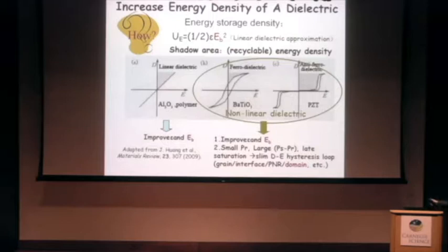At the same time, another key parameter you need to consider in the design is to make the applicable electric field as large as possible, because the energy you can store is not only in proportion to the dielectric constant, but also in proportion to the square of the largest field that you can apply to this dielectric capacitor.